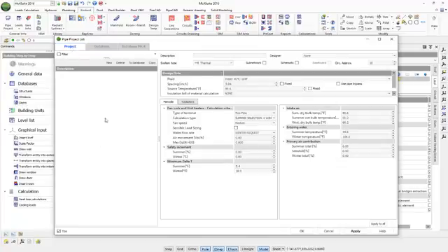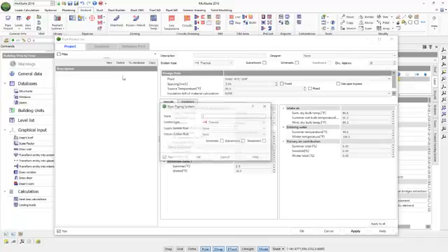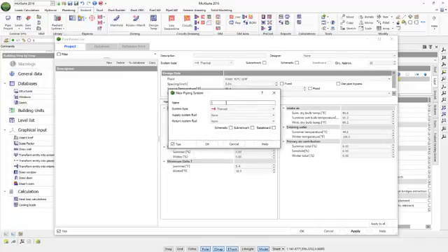And in our project tab, we have nothing selected. We can select New, where a new piping system window opens, and we can name our system, which in this case will be Radiant. And our system type, with the pull down arrow, we have different options to choose from: thermal, plumbing, gas, fire protection system, double phase fluid, and mechanical room. Since this is a Radiant system that we would like to draw, we'll use thermal system type.